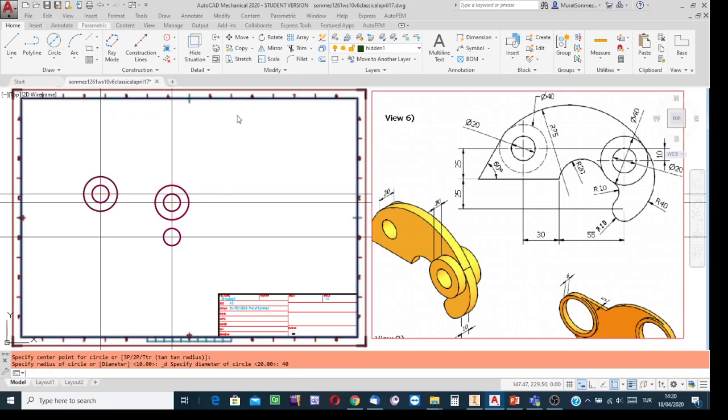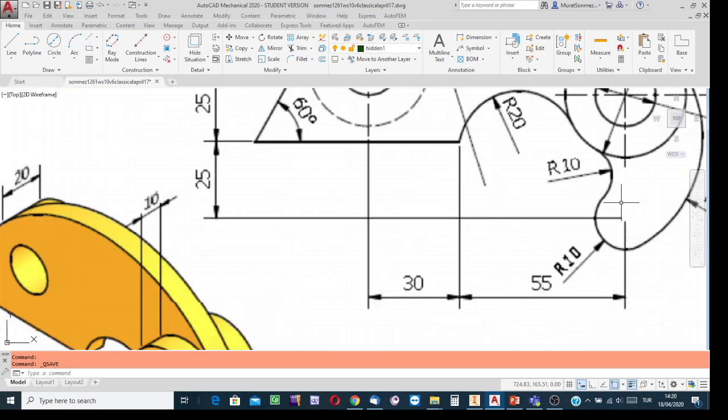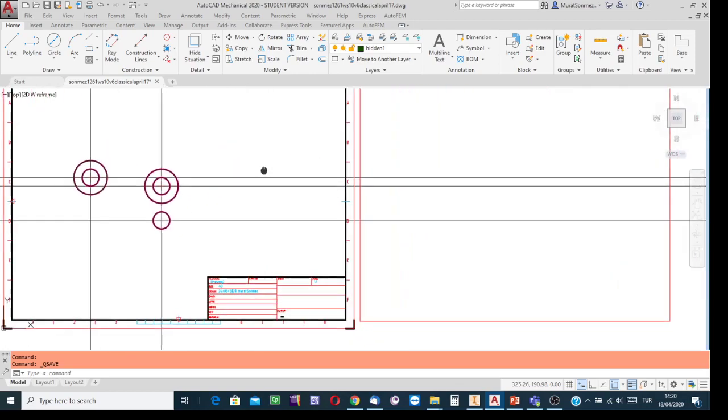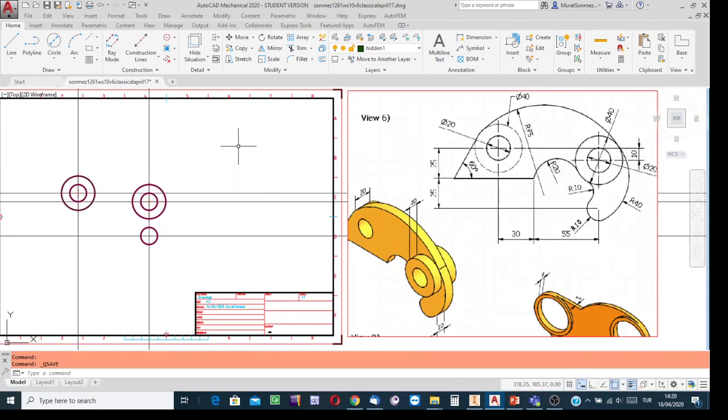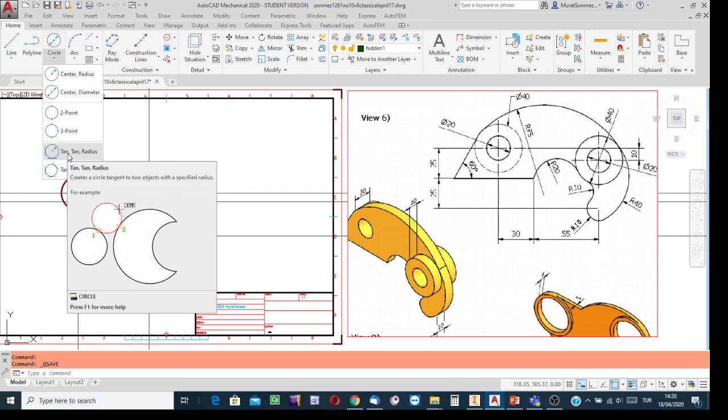Okay, save the file and then the rest, the other lines. Here there is an easy case to deal with. You see this circle arc. We have two tangent points, and we know its radius. With the classical method for creating such a circle arc, using the radius tool of the software, you can first create a full circle and then trim the further extensions. No need to draw any construction line.